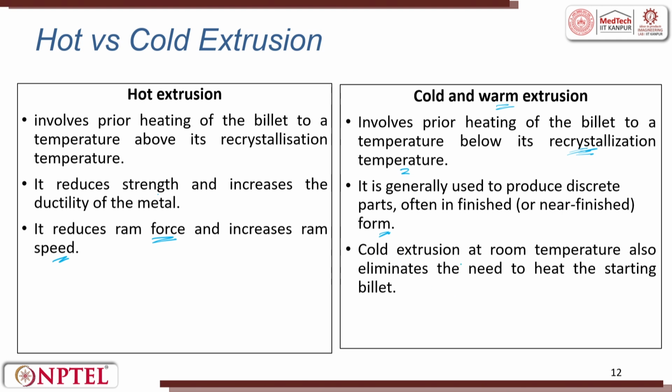Cold extrusion at room temperature also eliminates the need to heat the starting billet. Heating of the starting billet is expensive. Heating, increasing temperature, increases the power. By power, I am talking about the energy consumed. So, it is an energy costly process, hot extrusion.